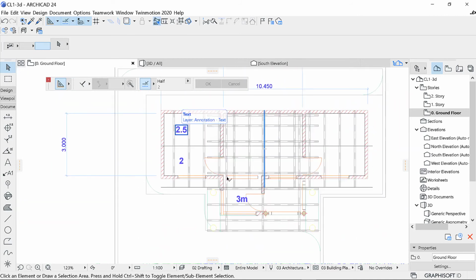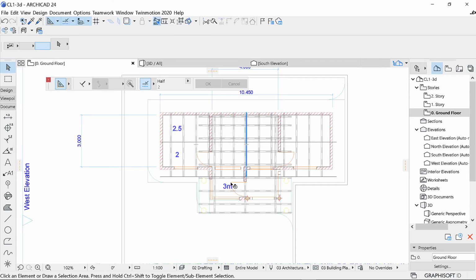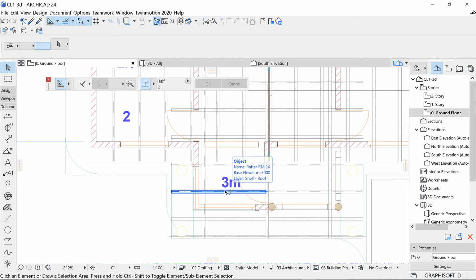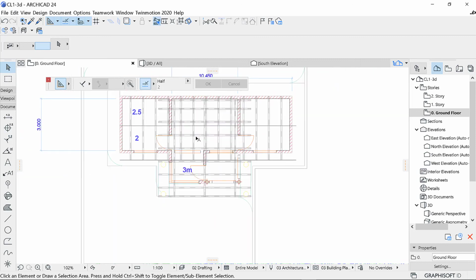Once you have that, the good thing is you have distributed your roof into smaller sizes, like you have 3 meters, 2 meters, and 2.5, which will greatly help you to reduce waste in your roof. Sometime later, maybe in another tutorial, we can look at how you can play around with the surface, the component schedule. You can determine the area of the roof, then calculate the roof sheets that you need, the size, which at times can help you know the percentage waste, like which size will give you less waste in sheets, and which one will give you more waste. Because this is BIM, and in BIM you can do anything amazing you want with it.